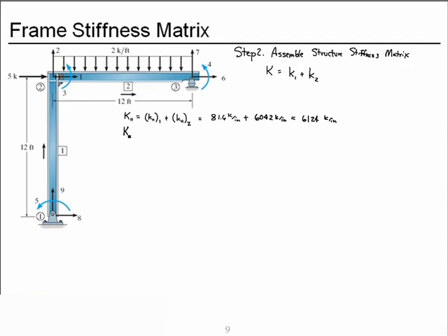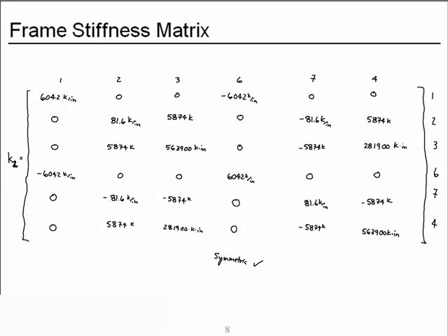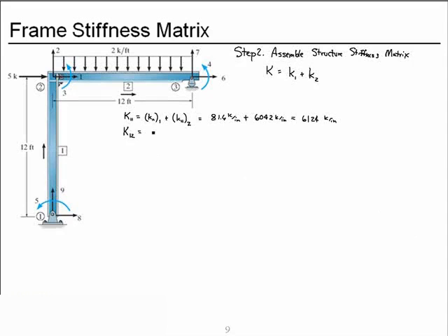So let's calculate those out here. We'll go to 1, 2 next. We know that we'll get it from each of these two elements. From element or member 1, row 1, column 2 is 0. And from member 2, row 1, column 2 is 0. So this coefficient, 0 plus 0, is 0 in the structure stiffness. Now coefficient 1, 3.